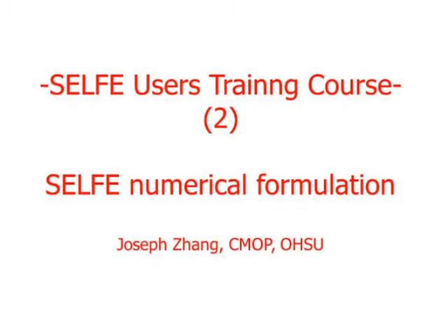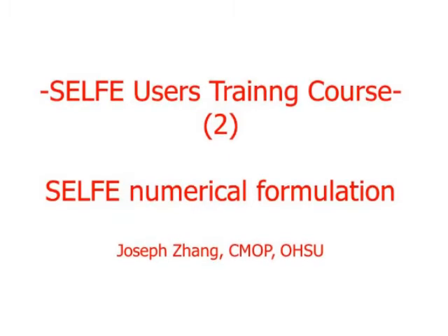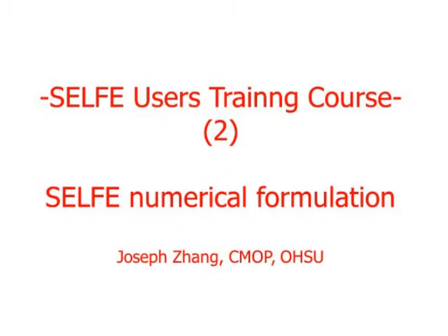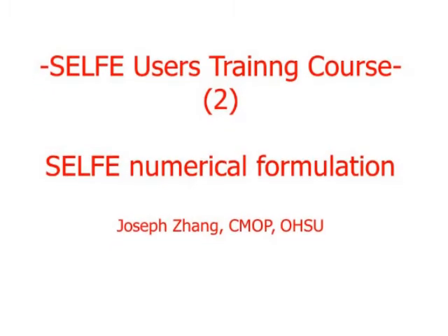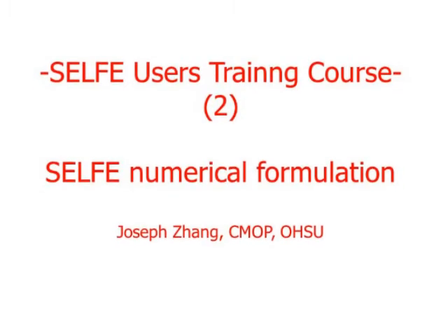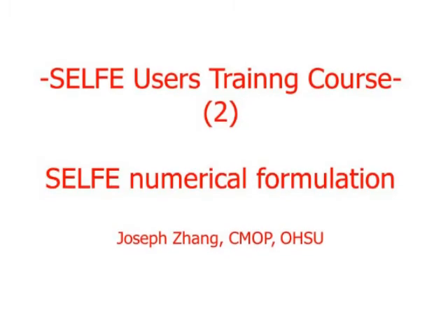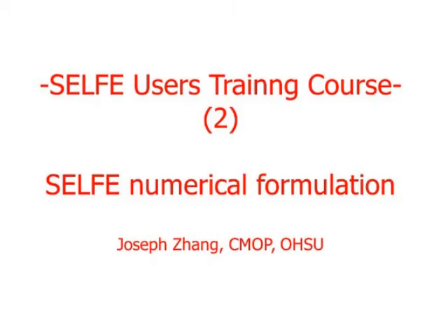So far we haven't talked too much about the source term, but very briefly, like slide 29. One particular source term, the body force, is due to the solar radiation for the heat transfer equation. For this term, we basically use a simple finite difference along the vertical in order to satisfy mass conservation.